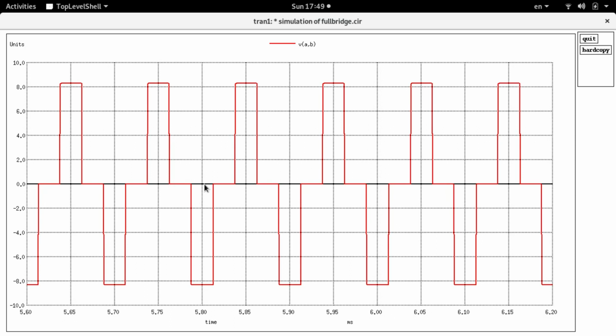And then when the non-dot end is positive, you have again on the other side the primary voltage. These two should balance each other, and during the time when all four switches are off, observe that there is no induced voltage across the coil. The primary voltages are 0.